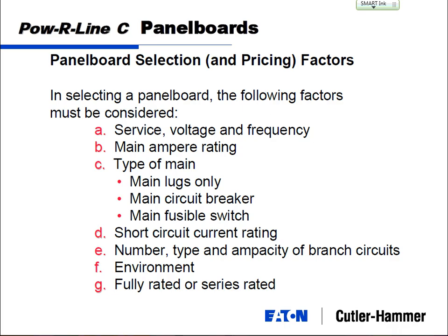Yeah. Well, actually, I've got a picture coming up for that because there's two things. You've got the equipment ground. A lot of times, you're going to ground the can, which is what you're talking about. You can actually take your building ground, I'll call it, and attach and bolt it right to the can. You can get by with a ground bar instead of using the can. So we provide that means still in there, because you're absolutely right, you always need some point of ground reference.